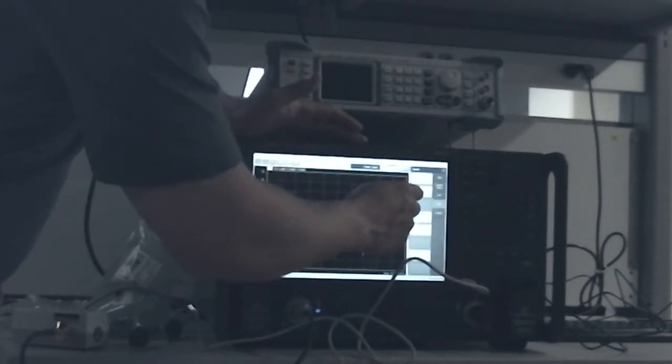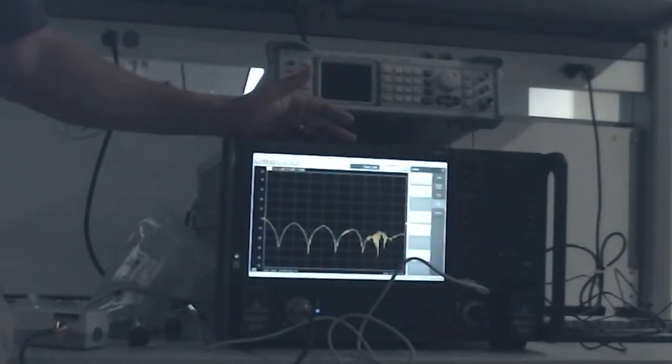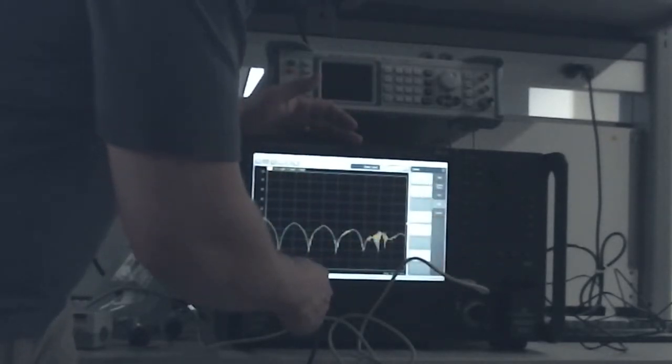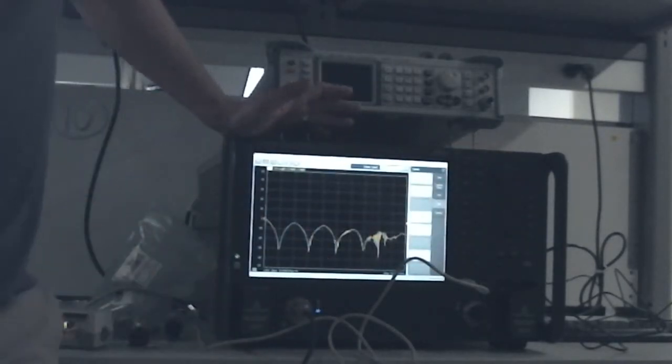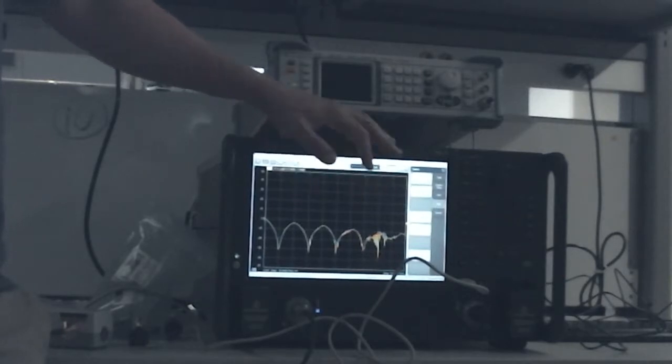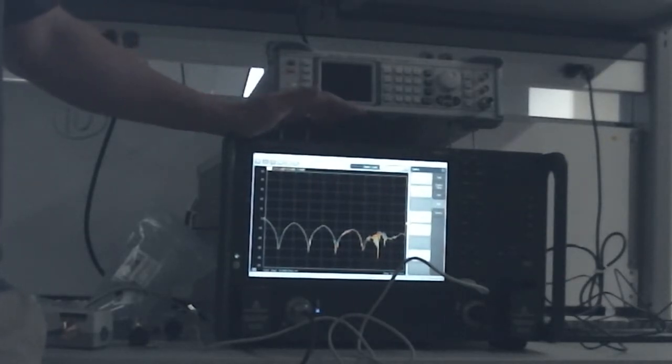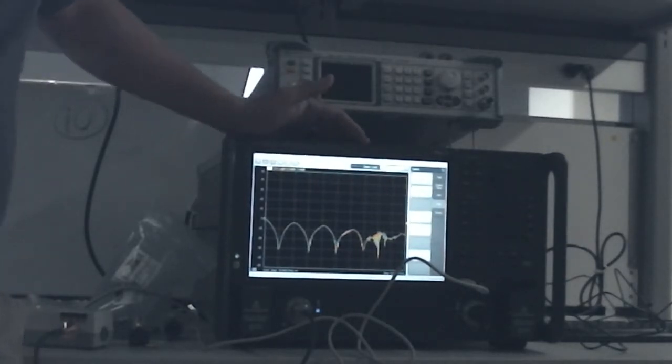But you could easily get 10, and there's no issues. You might even be able to get, like I said, about 13. That's fine. Probably anything above 13 dBm, I might see a warning come up saying source is unleveled, and that's where I would have some issues.